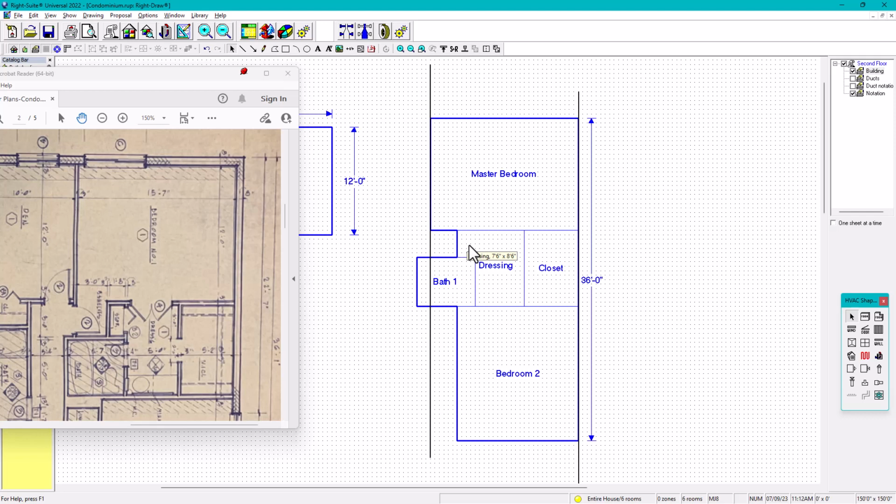And then finally, we need to add in here a small part for the bedroom, because as you can see in here, there is a door right here, so the master bedroom is not a rectangle. There is this small part in here, like some sort of a small vestibule, but not really. So we're gonna complete that part. I'm just gonna grab this. As I said, let's just put 1 number, because we're gonna merge it.